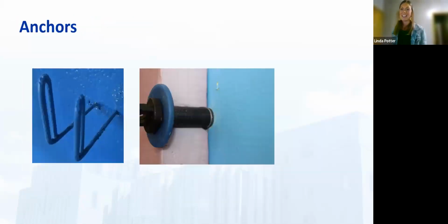Anchors, again. Who thought anchors, how you're keeping masonry on a wall, would be part of an air barrier discussion? But it is. Building envelope is the single most critical part of a building, in my opinion. And so anything that penetrates through or has any interface with it, we've got to understand: is it causing a potential for air leakage? We're seeing a movement even away from these hook and eye assemblies into post-installed sealed anchors to stop that air leakage if we're going to have to penetrate them. Make sure we have a plan for everything that comes through that, right?